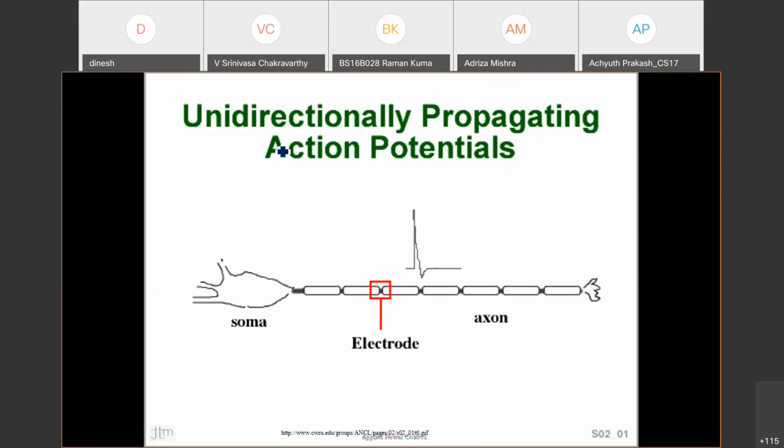So here one point that's important to notice is the voltage sensitive channels act like sources of energy, right? It is because of this nonlinearity acts like a source of energy, and that's why even in electronics, right, you have, let's say, amplifiers. Amplifier means what? You take a weak signal and amplify it. That means you're injecting energy into the signal without changing signal shape. How is it possible? Because of the electronic circuits, right? You cannot amplify signals using a passive circuit with an RLC circuit, right? So you need nonlinearity to amplify it.